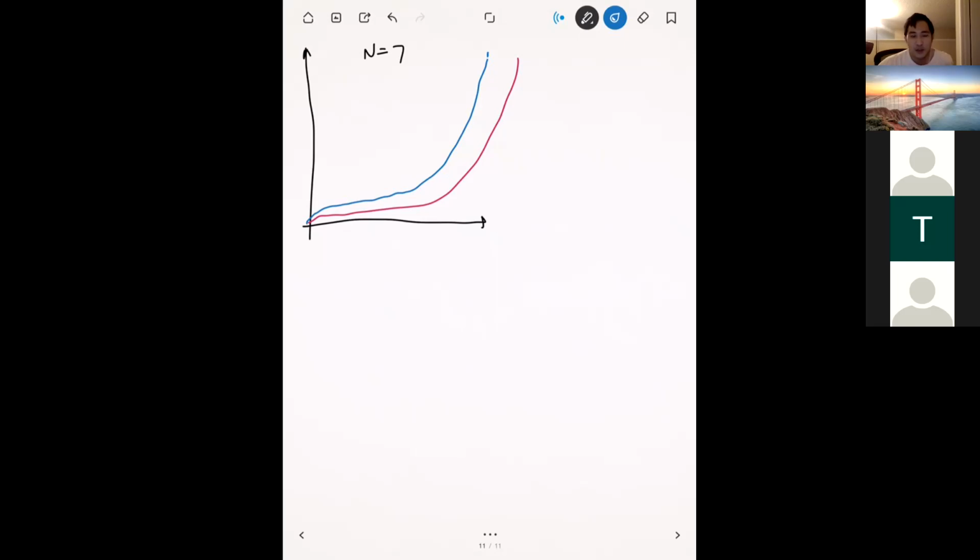I think even my computer can handle up to 1,000,000 grid points, and you can refine in order to make basically anything stable with central difference. But that's 1D. In 2D and in 3D, the cost of refining is a lot greater than in 1D, and it scales up exponentially. So in 3D, where a lot of people work with engineering simulations, refining the grid sometimes just isn't an option, because you don't have enough computing power, enough memory, or enough time.